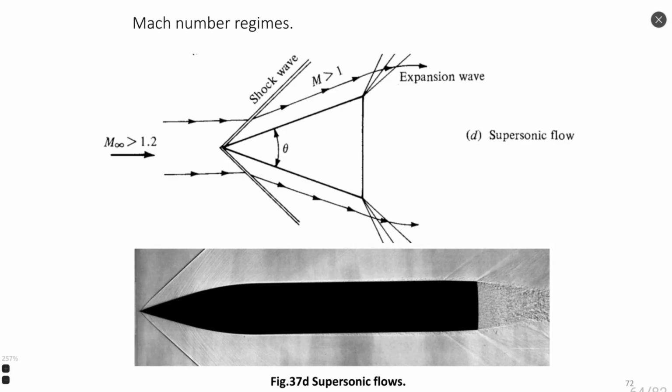We can start from some Mach number, could be 1.2, 1.5, depending a lot on the shape of the body, because 1.2 is not always enough to have supersonic flow everywhere. And then the flow passes through a series of shock waves, which change the flow structure significantly. This theory of shock waves we study in depth in gas dynamics.